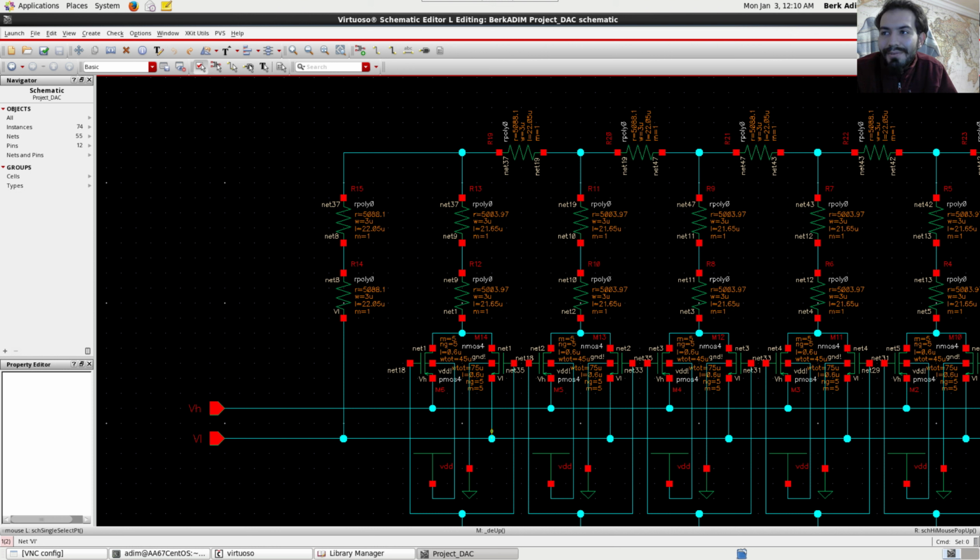One non-ideal characteristic of these transistors is their on-state resistance. When I turn this one on, or this one on, it will add a resistance to this net as a whole. And the differences here you can see are actually to compensate for that resistive change.